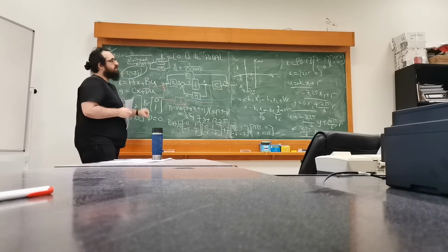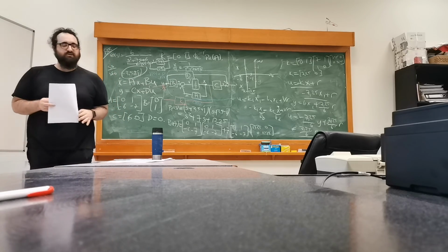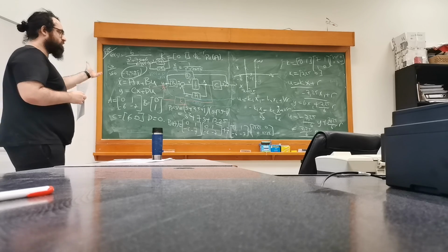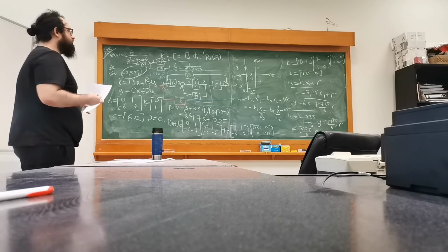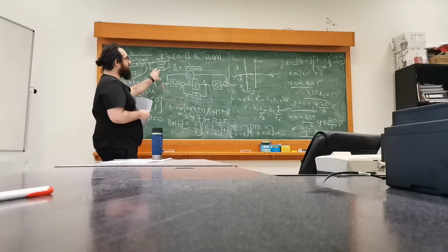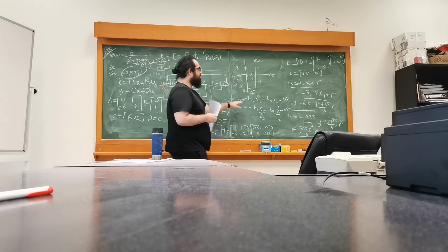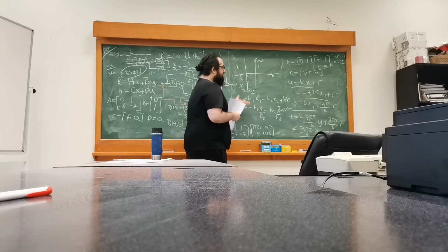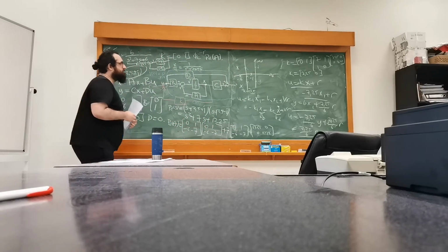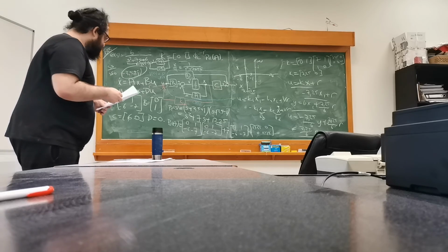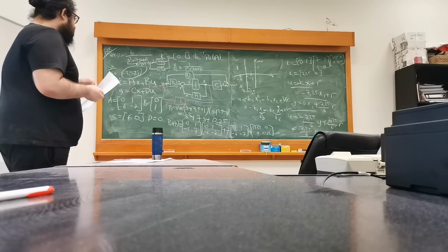But this part is an open loop sort of control or compensation. Therefore, it's not the best, but you get the idea. The pole assignment corresponds to a feedback PD control for a 2x2 system if you have K1 and K2. If you are on the root locus for p-type controller, your state feedback will be a p-type controller. So that's basically it. And this was question 8.